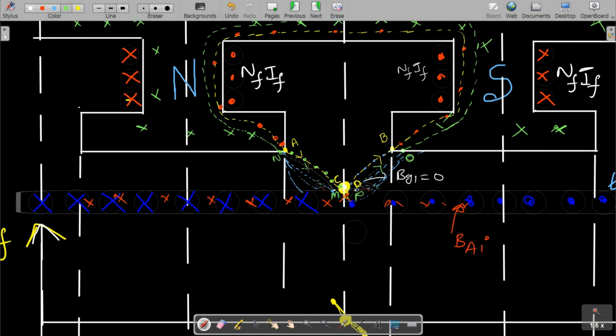The thing is that as we move from the q axis to the north pole on this side, what are the flux lines we are taking? These flux lines here, here, here, like this. No, these lengths are decreasing when we go from the q axis to the north pole side. And similarly, on this side also, these flux line lengths are decreasing.